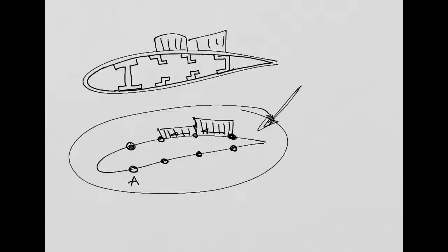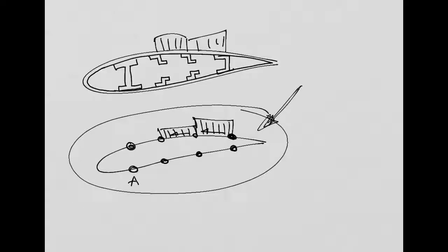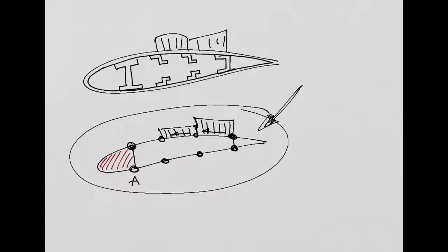Now, before we do this structural idealization, we need to discuss a bit on torsion, okay? Because the reason is, and I forgot to say here, for example this part, I forgot to include this. These parts here will divide the cross-section into what we call cells, all right? These different cells. So I'm going, for example, to say this region here of your wing is what we can call cell number 1. This other region here between this part with I shape and this part with C shape is what we can call cell number 2, our second cell. And this region here is going to be another cell, number 3. Okay?